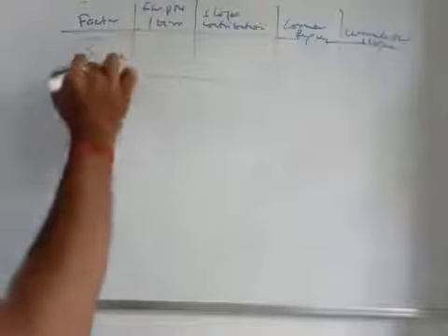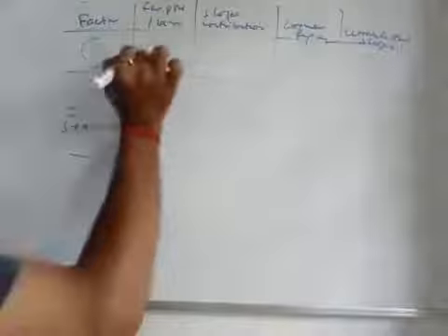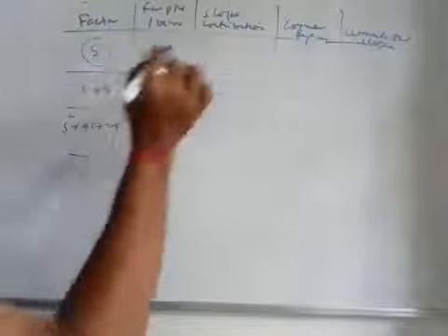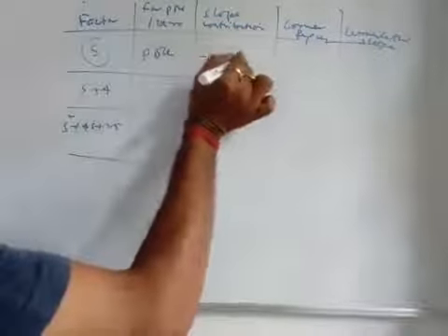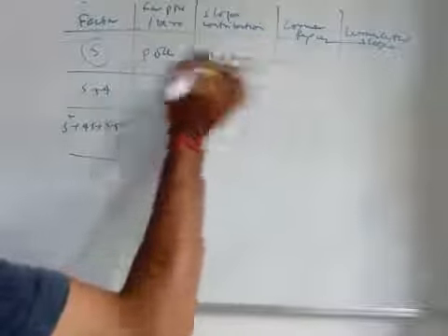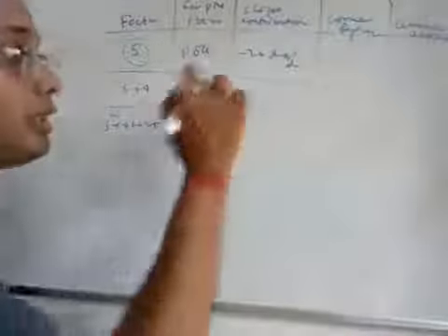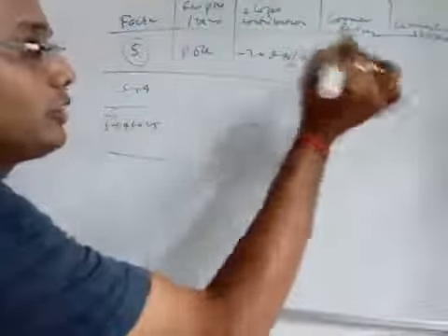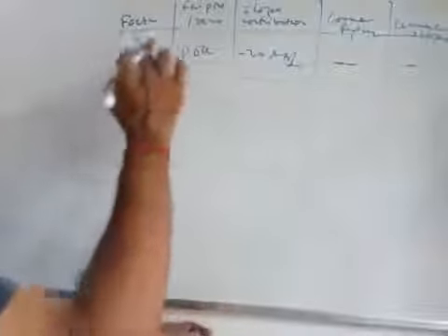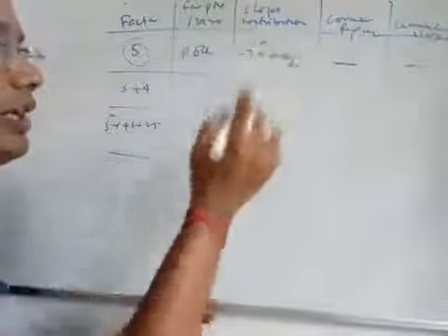So this is the factor s. This is a pole, there is no problem, and the slope contribution is minus 20 dB per decade. Now see, this is s, that means there is no chance to get this structure like 1 plus sT. So there is no corner frequency. That is why this is a type 1 system, and the initial slope is minus 20 dB per decade, right?